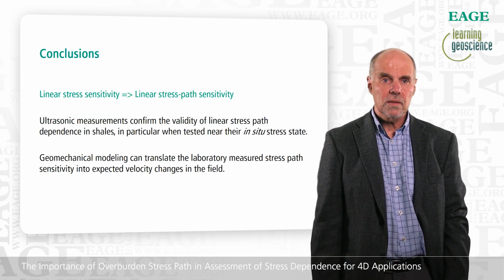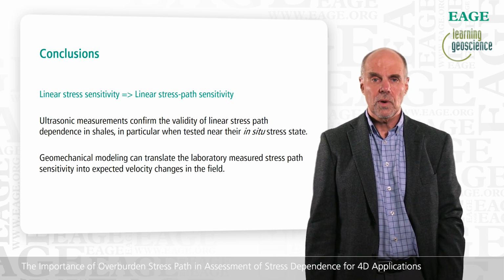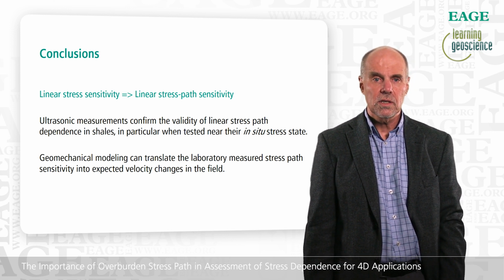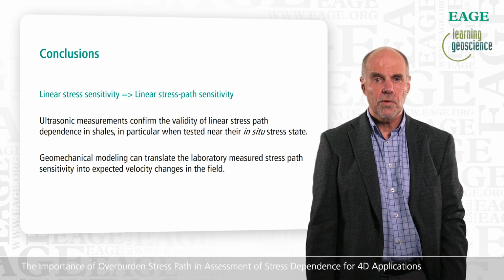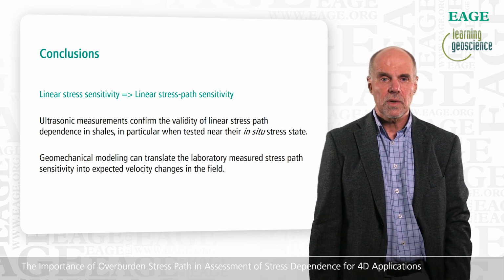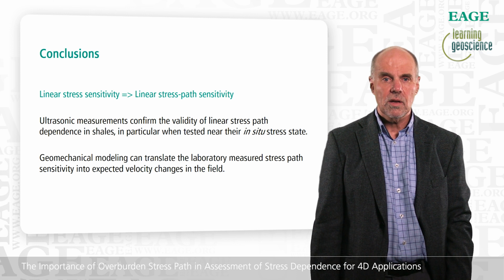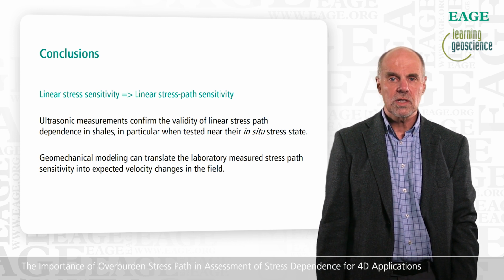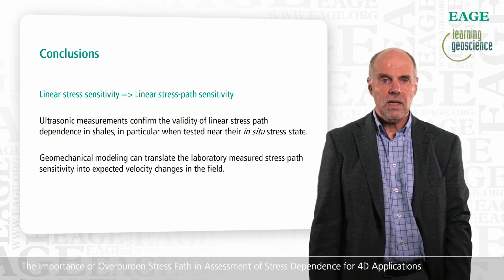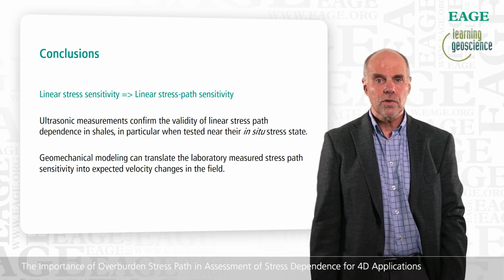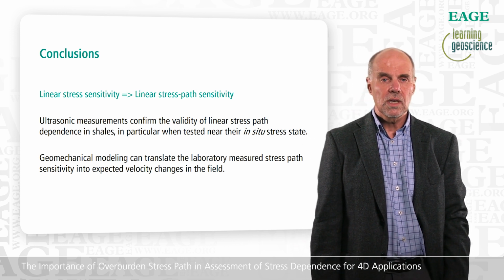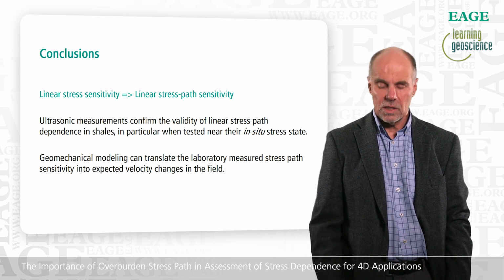So conclusions then. Linear stress sensitivity implies linear stress path sensitivity. Ultrasonic measurements confirm the validity of the linear stress path dependence in shales, in particular when tested near their in situ stress state. And geomechanical modeling can translate the laboratory measured stress path sensitivity into expected velocity changes in the field.